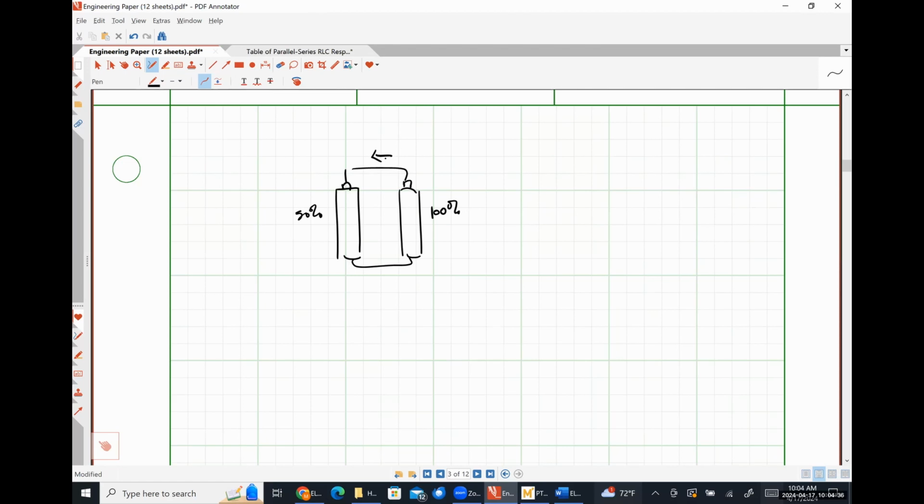Yeah. So a thermoelectric generator is what you're specifically looking for if you're trying to harvest heat energy and convert it into electricity. The problem with those, and I say that as a senior design teacher who's had several groups try to use them, is that the temperature gradient needs to be very large to get any useful voltage out of it.